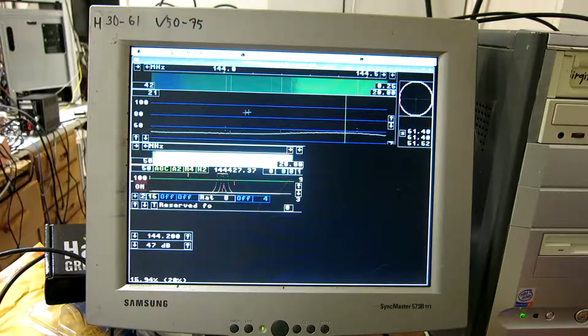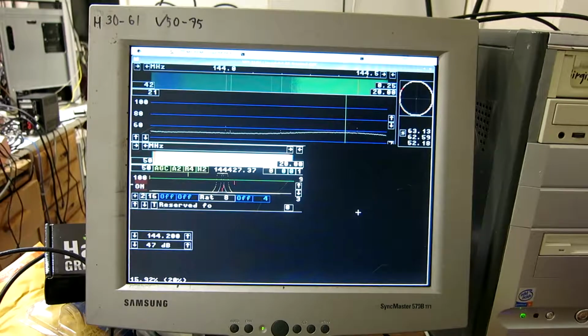You can see now that the signal, let's say the noise floor, is at 50 dB approximately. That's a very high noise floor. That is because this is an 8-bit AD converter, which means that the result is shifted by 8 bits at the factor of 256.